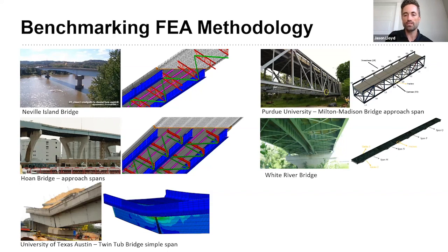A 6th structure, the Dan Ryan transverse cross girder that fractured in the 1970s, was also used to develop the dynamic amplification factor. Once the necessary FEA procedures, techniques, and inputs for the redundancy evaluation of steel bridges were established, the FEA methodology was completed with the development of load case characterizing the loading conditions during and after the failure of a steel tension member, and then also the establishment of performance benchmarks that guarantee redundant capacity in the faulted state.